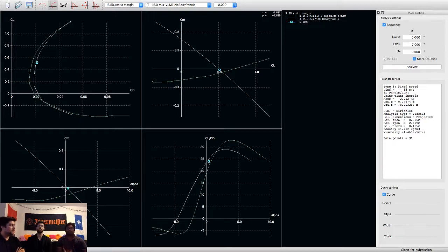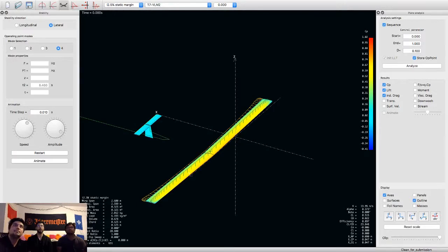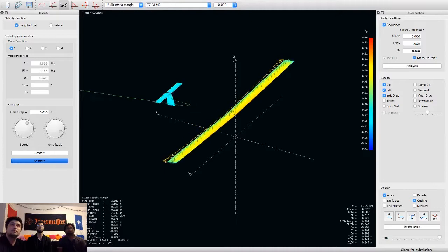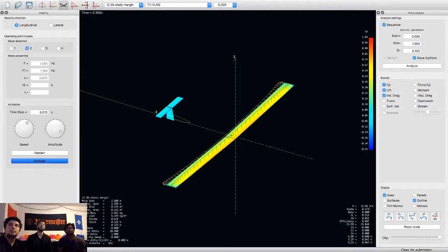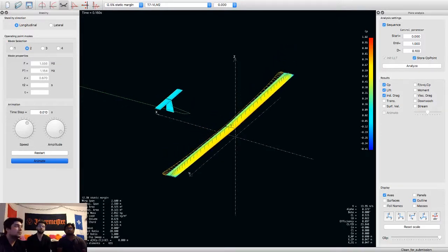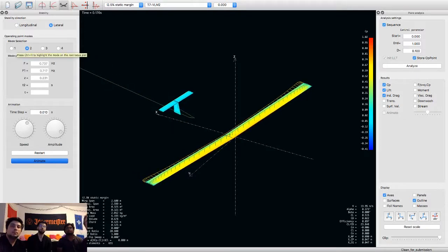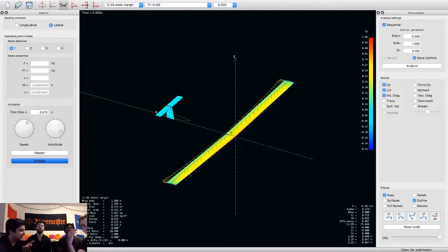And after that we went to the dynamic stability, which is calculated directly from our XFLR simulations. As outlined in the report, we're not going to show all of them, but absolutely all the modes are stable, with the exception of the spiral mode, of course. One thing to note is that the roll subsidence mode has an eigenvalue of about -1000. As you can see, it's quite fast.